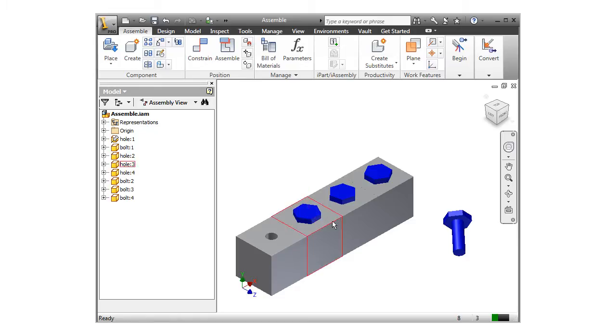It's also possible to change the constraint type after you start the process. Again, release the Alt key, and you can then enter a shortcut. Be aware that sometimes you have to hit the Alt key again before typing in the shortcut, because normally the Alt key is used to enable quick access to the menu and ribbon commands. This functionality is enabled if you see the keyboard shortcuts pop up over the menus.